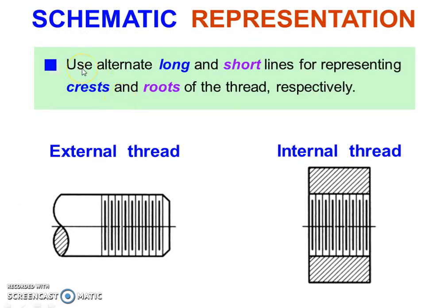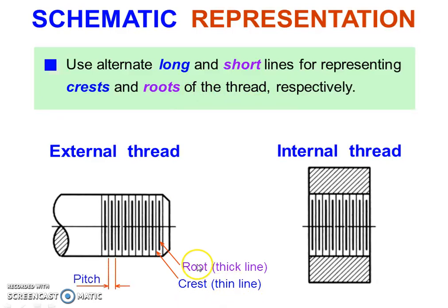Schematic representation. Use alternate long and short lines for representing crest and roots of the thread respectively. Crest is represented with a thin line and root is represented with a thick line, over external threading as well as internal threading.